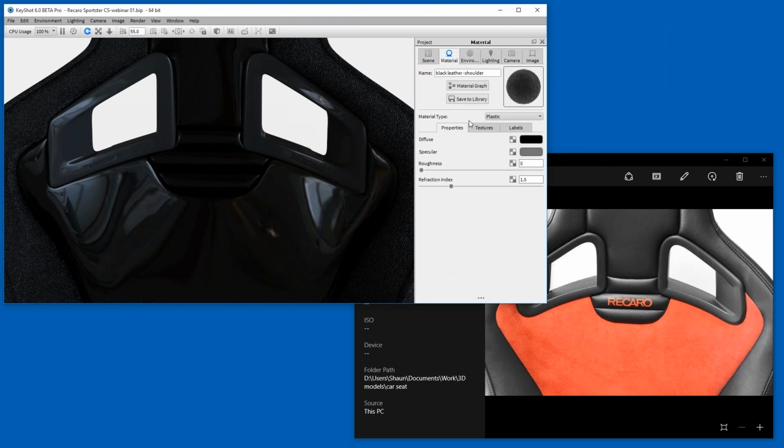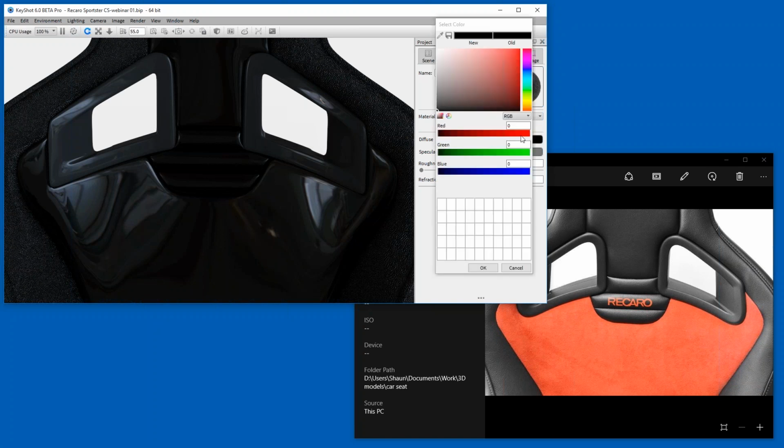On that note, I'm going to look at the material of the leather, which is a plastic material, which is good. It has a nice shiny quality. I'm going to take the diffuse color, which is again default, absolute 0 0 0 black RGB values. And I'm just going to raise that a little bit off from total black. And that will sell the material as being real later on as we add all these little elements to it.